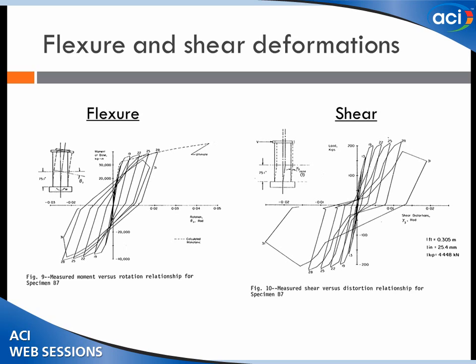And what one finds is that when the wall yields in flexure, it yields in shear. Even though the wall is reinforced such that the shear strength is greater than the shear corresponding to flexural strength, this is controlled by flexural yielding. Even though it is, there's inelastic shear deformation that's occurring. And to this day, I don't think any of the software that's used widely by practicing engineers picks this up. It's sort of been lost.